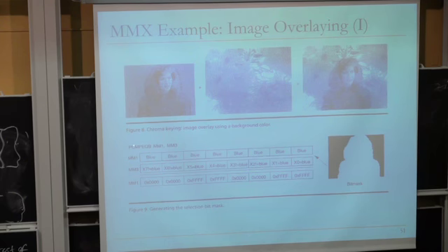So Intel MMX provides a packed compare equal byte instruction, which takes one 64-bit register, let's say 8 pixels from this image, and 8 pixels from this image, if you will. What we want to do first is figure out whether these are all blue. So we take 8 pixels from this image and compare them with all blues. The 8 pixels from this image go into multimedia register 3, and we have blues going into multimedia register 1.